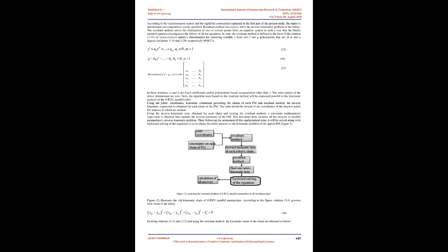The first hinge joint, located at point A, belongs to the fixed coordinate system positioned at origin point 0 at distance a. Also, the first universal joint is located at point B with a distance L from point A. The link always moves on a plane whereon the vector is perpendicular. Therefore, the coordinates of points A and B in coordinate system 0 are as follows. The mobile platform has been connected to the robot via 4 universal joints situated on points Ci.